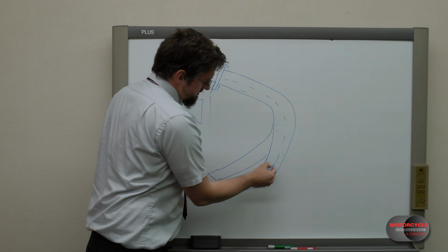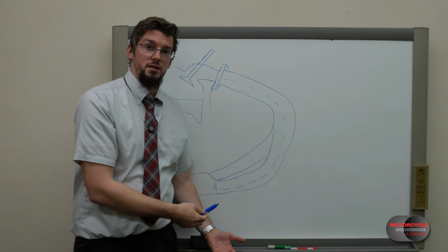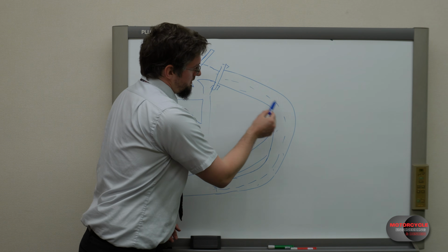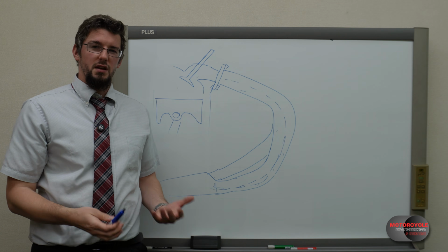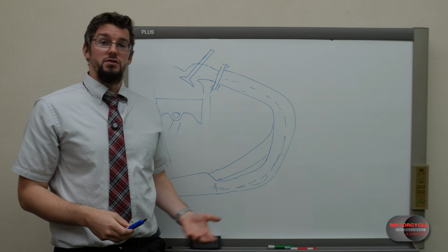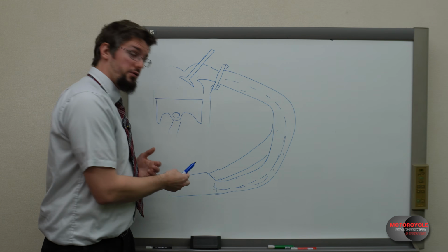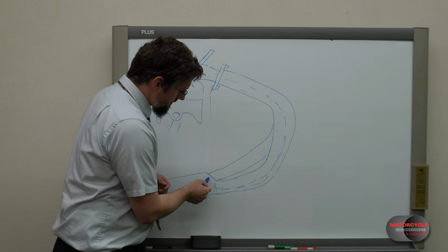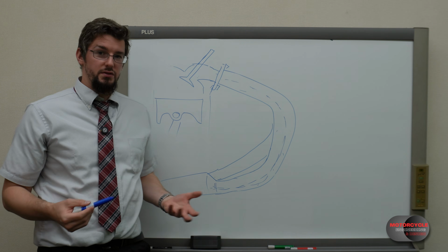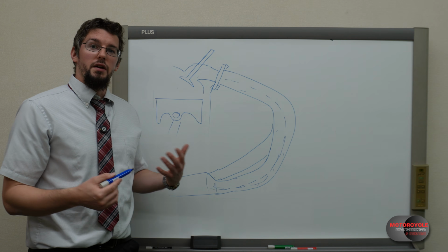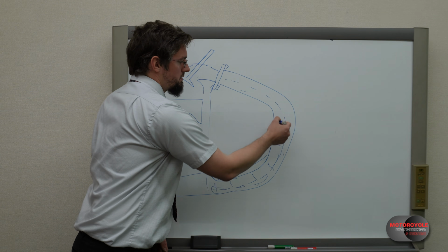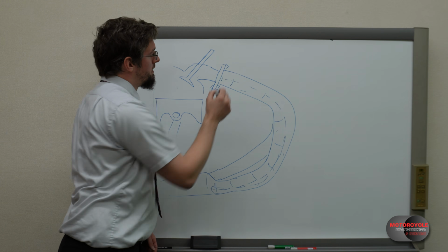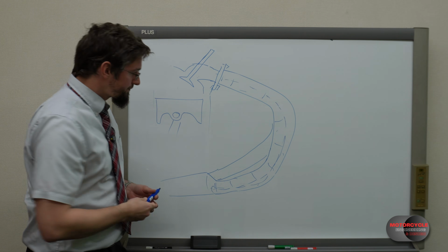As the exhaust flows down here, we're going to reach an expansion. When a flow of gas or fluid reaches an expansion, but we maintain the same volumetric flow, we're going to have a drop in pressure. That drop in pressure results in a kind of rebounding negative pressure. This is like a pulse, and it's going to pulse back to the exhaust valve.